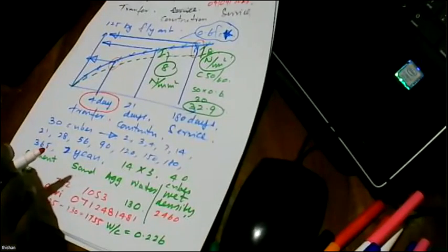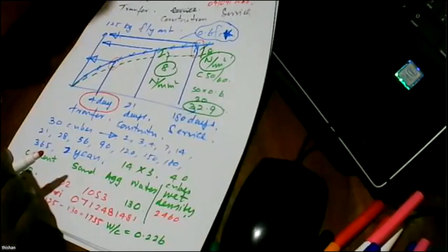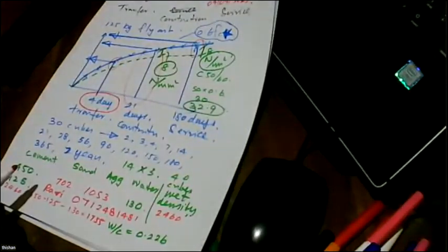If we have only the self weight of the beam, you have to introduce an additional level of calculation, and that is the construction stage. What is going to happen to the beam during construction and immediately after construction? Because that's also important. Just when you place the beam, it will not end there. You might add a little bit of additional concrete and load it, but you are definitely not going to get the HA and HB type vehicles, or the normal and special type of vehicles. You are not going to get it.